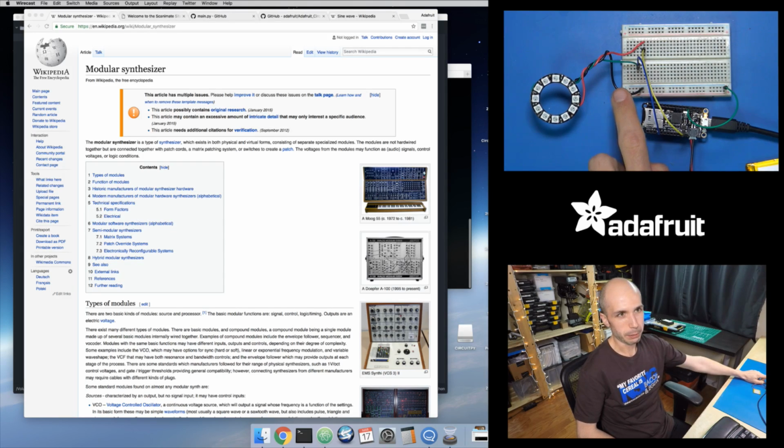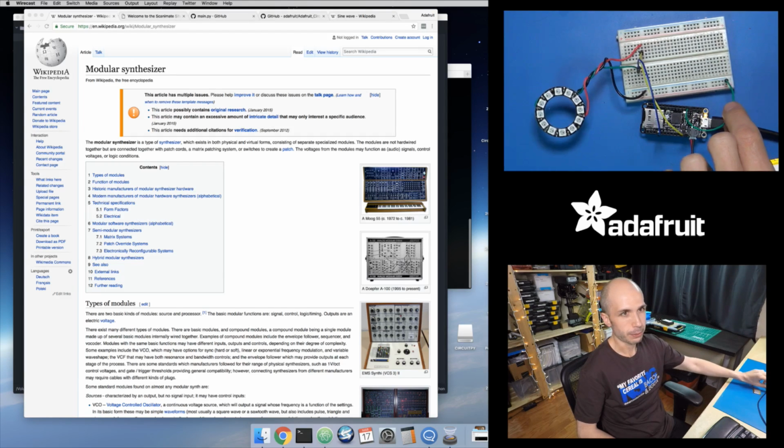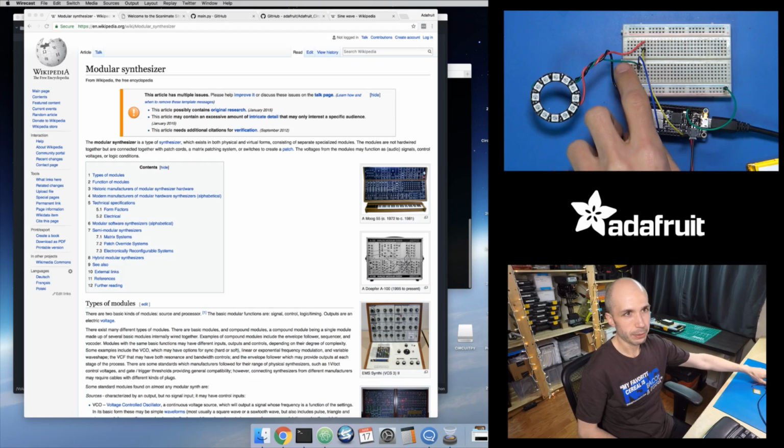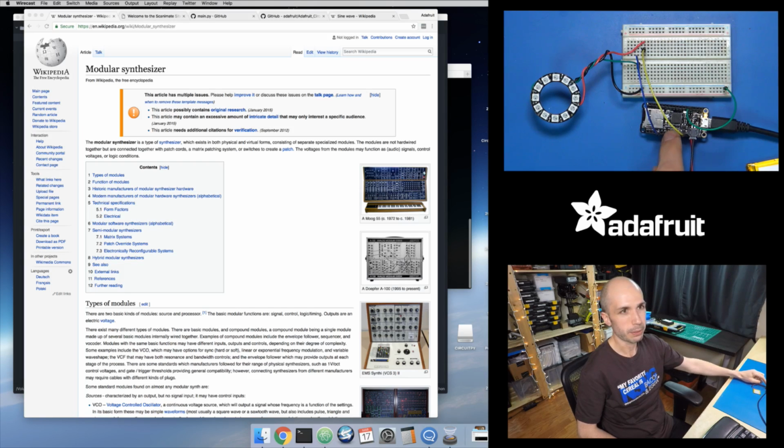You'll need to wire this to your board. So I have the ground connected to the ground of my board. It's through this little green wire that goes to my breadboard, because we'll come back to why I have a breadboard here later. We're going to add some extra components. This green wire is the signal, the data input line to the NeoPixel. That's connected to a digital I/O line. This is D6, digital number 6 on this M0 board.